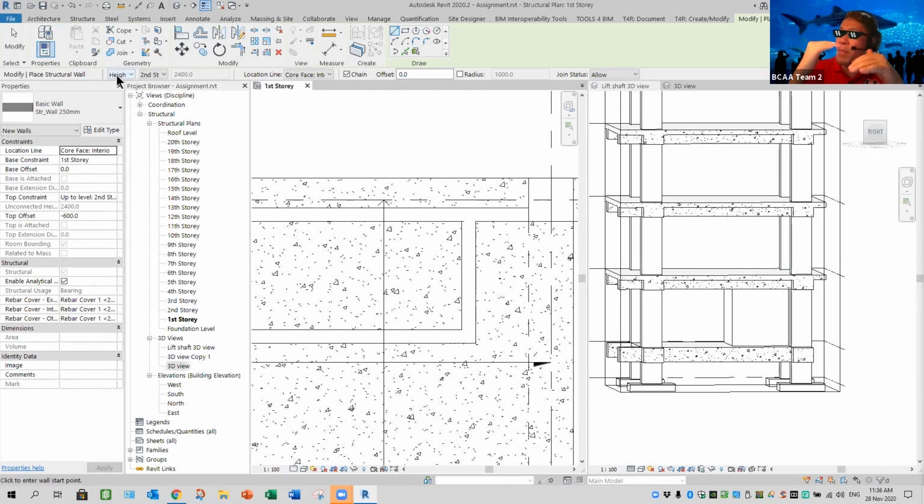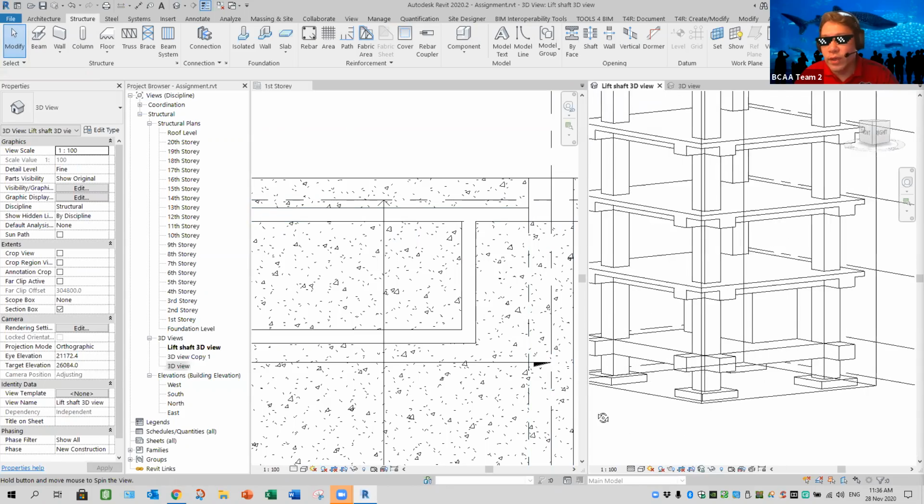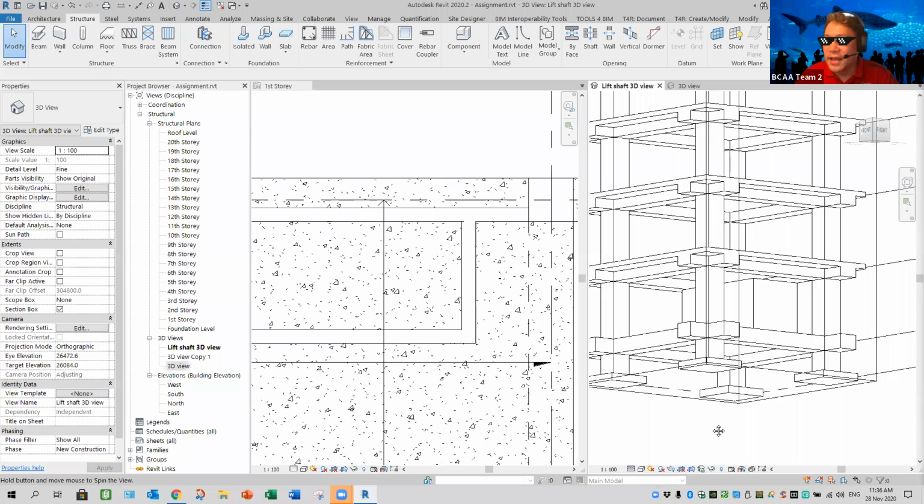So that means I prefer the architectural method of construction. You can't, because by default when you draw at first story, you go to foundation, because this option bar here is set or defined as depth. So you need to go to your 3D view to move it up. Change the level if it disappears. That's it. Not difficult, don't worry. You just got to get used to it.